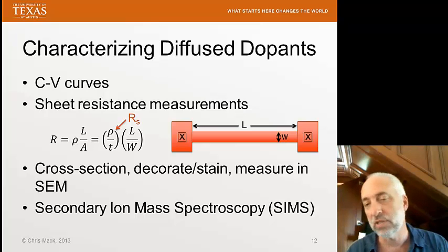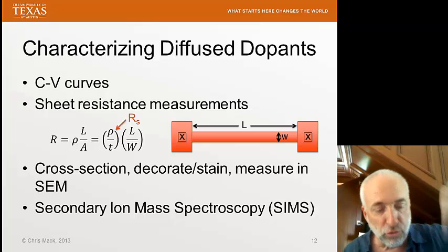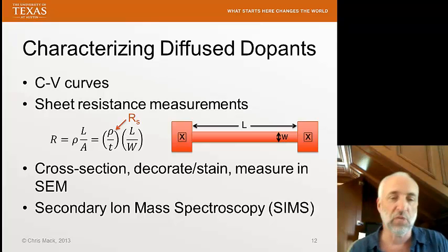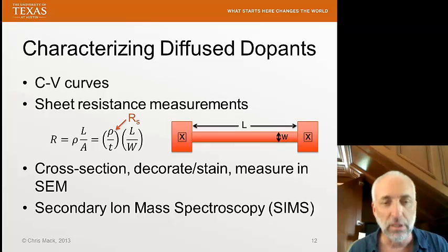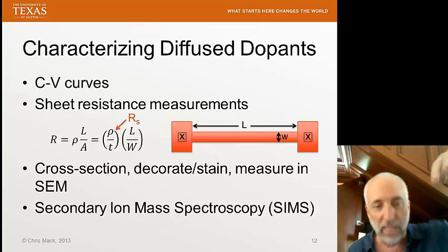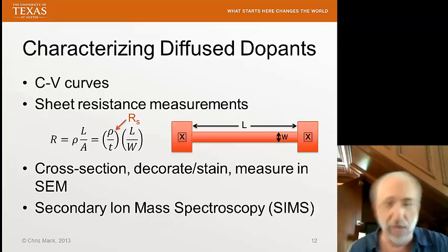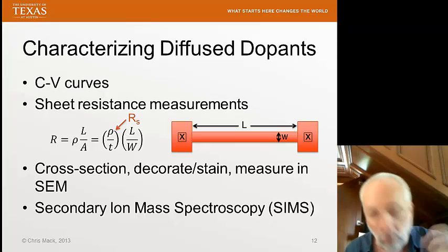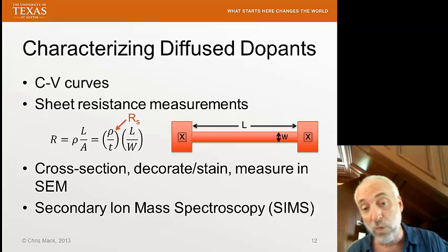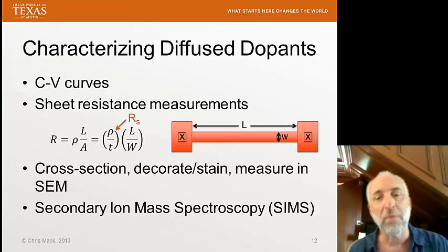What we do here is in conception very simple. I take a beam of ions and drill a hole into the silicon wafer. I'm doing ion beam etching. We'll talk about etching later, and you'll learn exactly how this etching occurs. But basically, I send ions down, and it acts like a sandblaster to blast away bits of the silicon and drills a hole down. I take the bits of silicon that are flying out and put them through a mass spectrometer.